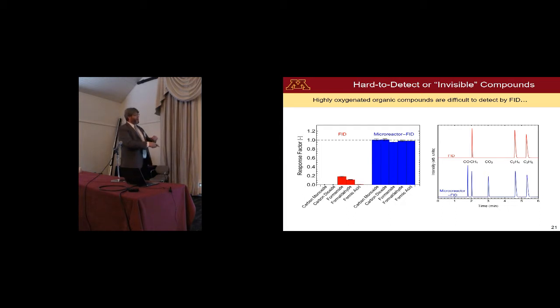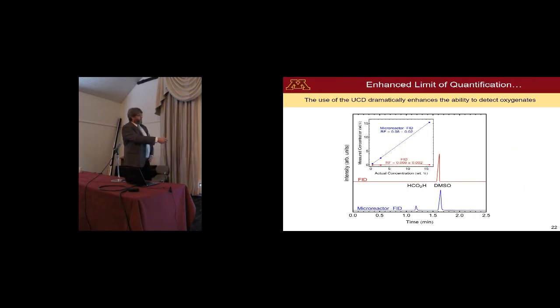If I look at the two chromatograms side by side, here in blue you can see all of the species that show up because they are now fully methanated, and on top, only a couple that you would anticipate give some response. And now you can see what I was talking about earlier. When you use this 3D printed microreactor approach, you get this nice resolution and very nice peaks remaining with a negligible shift in the GC. You can see this too when you look at it a couple of other ways. There are other peaks here, and you can look at the measured concentration versus the actual concentration. You get this nice parity between the two with the microreactor FID, whereas in a conventional system you do not.